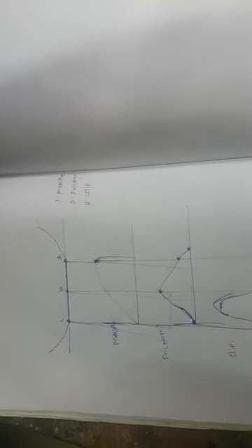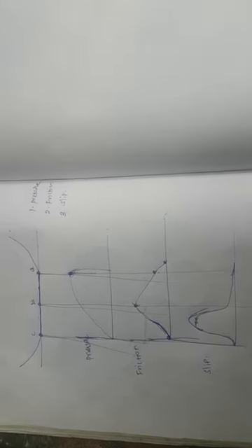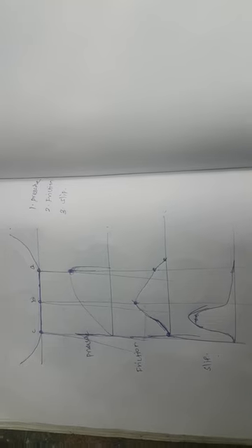And if the tread comes to point B, the center point of the tire, it develops maximum friction, and when it comes to point C, the trailing portion, it actually slips, right? So maximum pressure at the leading point, maximum friction at the center point, maximum slip at the rear point, the trailing point. This is what we have discussed till now from our classrooms to part 1 and part 2.